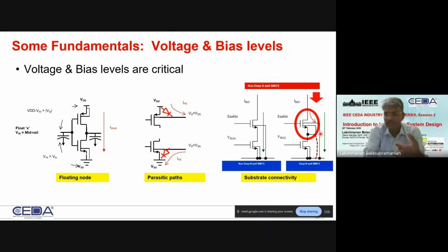And the third one is, as I talked about, there are different types of NMOS devices, isolated and unisolated. There are 2 NMOS devices I'm showing here. One is isolated, the other is unisolated. They may be called a device with a deep N-well, and a native device in a P substrate. Those are 2 different kinds of NMOS devices. They may be used for noise isolation purposes and threshold control purposes. But when different types of devices are sitting in a single chip for trade-offs and circuit optimization, it looks like silly mistakes can cause huge catastrophic issues, right?